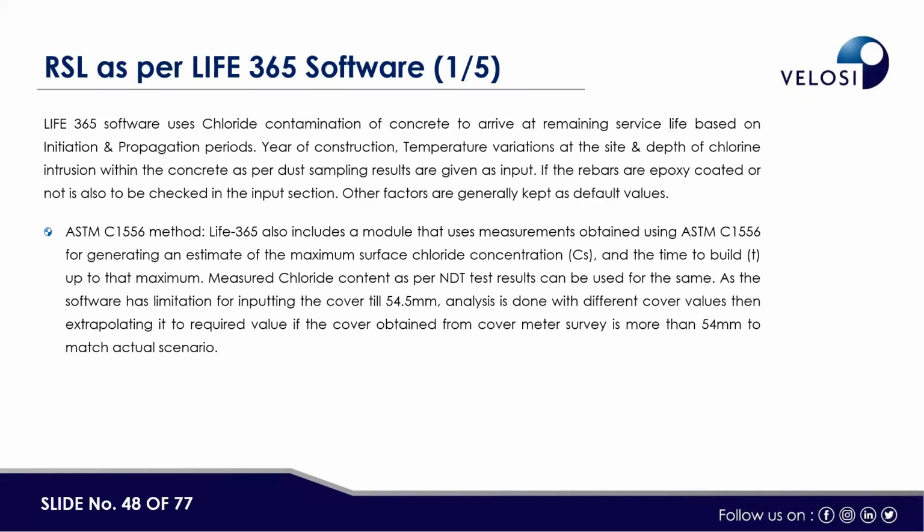This bulging could cause crack formation. Tension cracks will be formed on the cover surface. Once this reaches an unacceptable level, the spalling will start taking place. Spalling is the last phase, where the rebars are completely attacked, the rust is formed, and the volume increases considerably at that period.